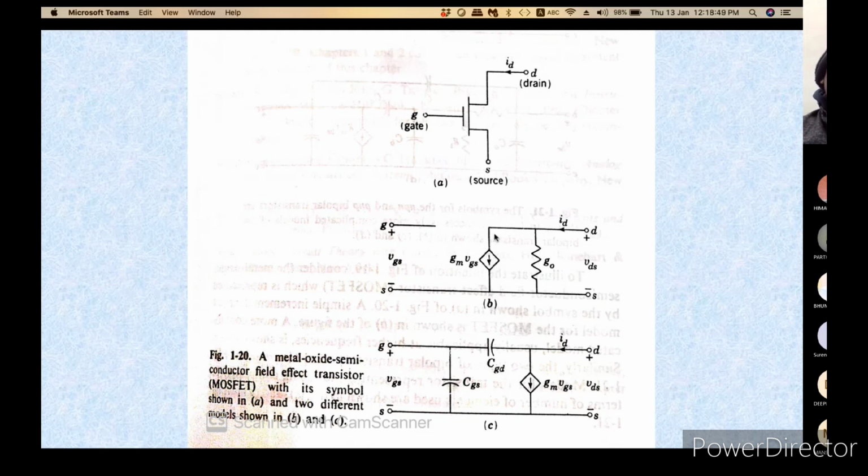So from drain to source, it acts as a current source, and not only that, it is a voltage controlled current source. So they are again different. If it is a voltage source, then just a plus minus sign is given. But if it is a current source, then the direction is also given inside. When we continue, we will try to know different symbols also, and then at very high frequency you have to consider the junction capacitances and all that, which I have already explained, okay.